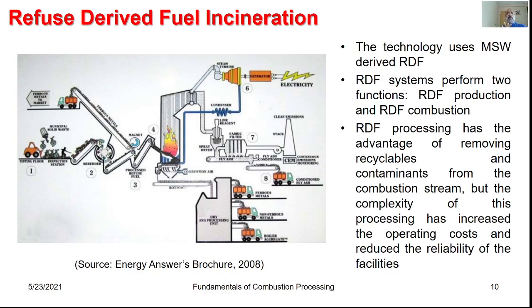The second facility is refuse derived fuel incineration. Most of the processes that we discussed are valid for the earlier incinerator. Here, the only difference being the facility itself, as it receives the waste, some of the waste could be separated, which is beneficial in nature, and it could be transformed into the powdery or pelleted RDF, which would be used as fuel in the incineration operation.